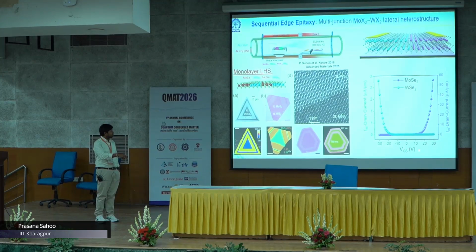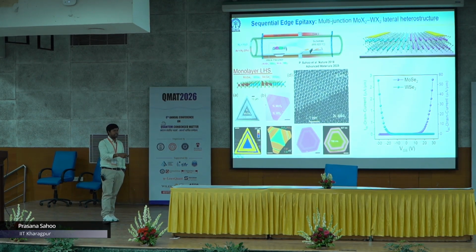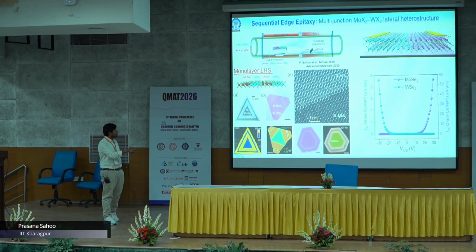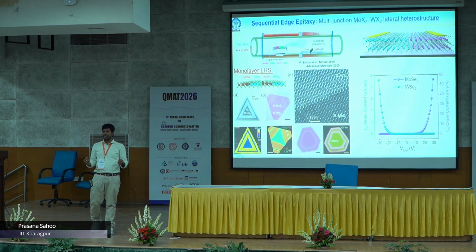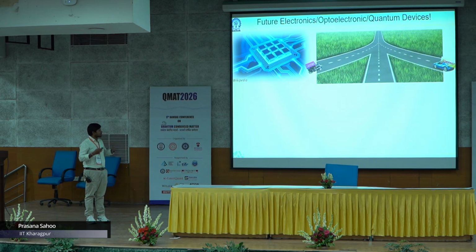By applying gate voltage, one can populate more electrons in the domain. It's called electrostatic doping, making it N-type, or the other which indicates a P-type. That indicates one can indeed grow a PN junction diode directly using these CVD methods. And later on I will show you what the prospective applications of these things are. What is the future of these 2D materials?